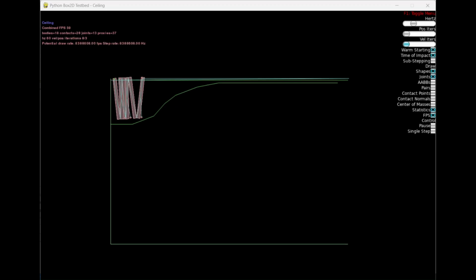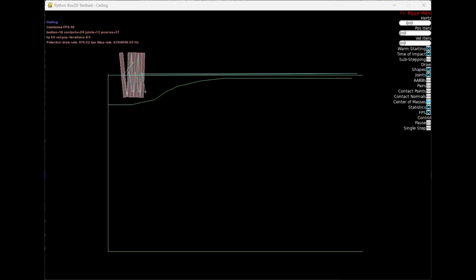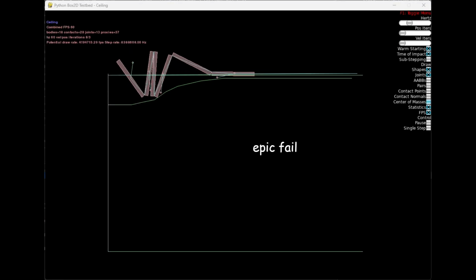As they move outward and contact the rail, it applies a normal force to the lower wheel, so the panel rotates as it rolls up the rail. I call this the train design. This worked pretty well, except that when we get to that last pair of panels, we run into the same problem. The rail can't help out with that one, and we can't apply enough force to pull it flat. But this seemed like it was on the right track, so I kept investigating how I could use more rails to achieve the kind of motion I wanted.